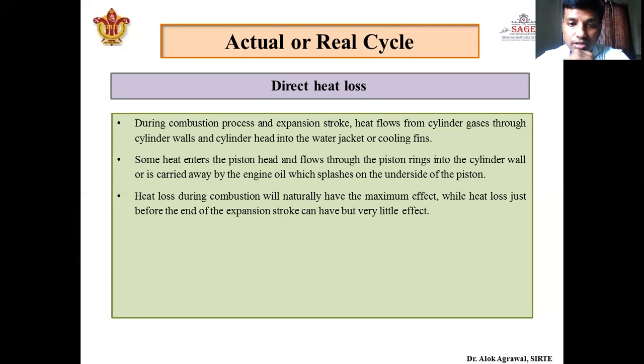But the heat lost during the end of the expansion stroke has very little effect, because the tendency of that heat to be converted into work is minimum. So heat lost at the beginning of the power stroke has maximum effect, and the heat loss at the end of the expansion stroke has very little effect.